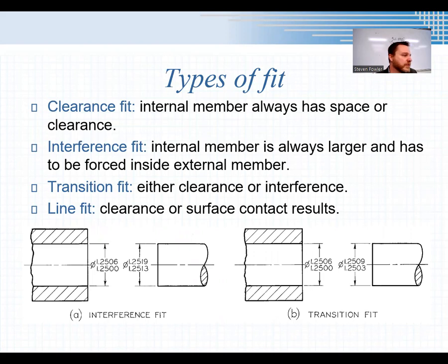If it's acceptable to apply a large amount of glue to the two, if I need to really seal them up, or if I'm going to weld one to the other, right? So I know I'm going to use some other means to join them, not just pushing them together through friction. A transition fit would probably be acceptable in some cases like that, right?